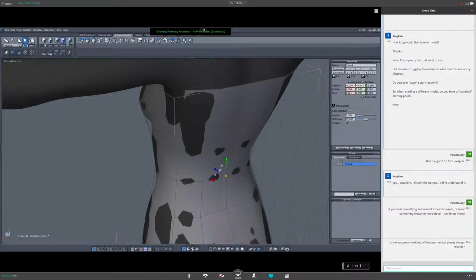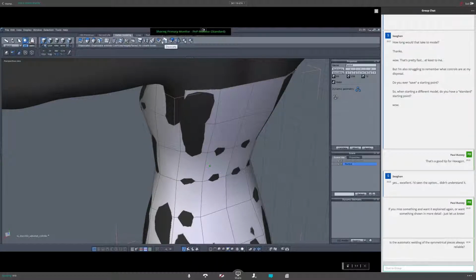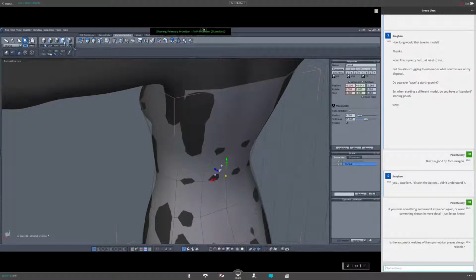Or if you're creative, you go up here in the Properties tab, in the Size tab, and enter 0. Now you just re-weld and it should have closed. You see, it didn't close the hole. There are ways to fix this.